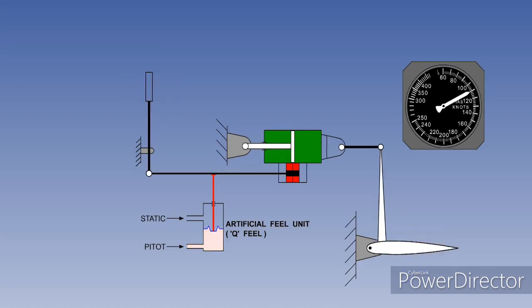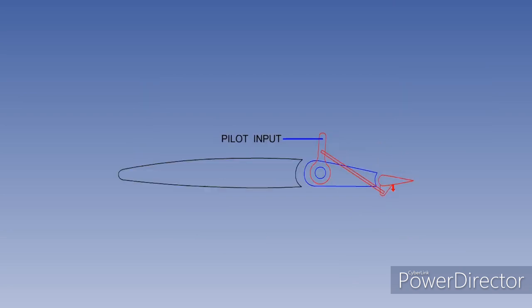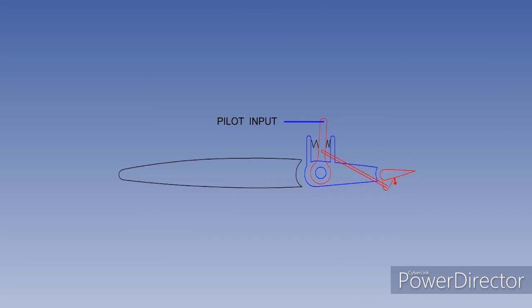If hydraulic pressure to fully powered flying controls were lost, the aircraft would become uncontrollable. So some alternative means of control must be provided to guarantee safe flight. This can be done either by manual reversion or designing redundancy into the power flying control system. Manual reversion can be achieved by either servo tabs or spring tabs. In the event of hydraulic failure to the PFCU, a valve automatically opens to provide a path for the fluid across the piston. This cancels the hydraulic lock and allows movement of the control surface by either a servo tab or spring tab.